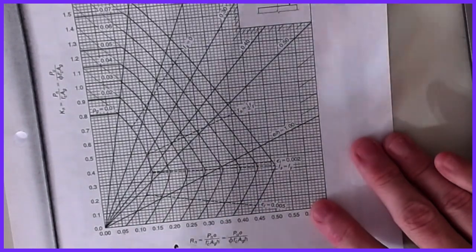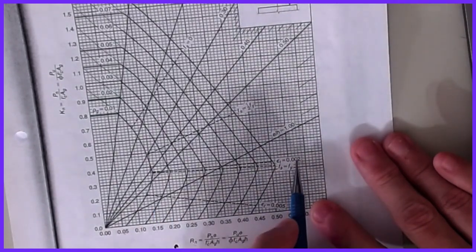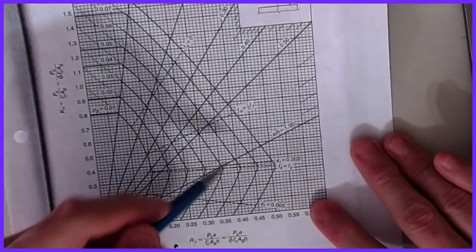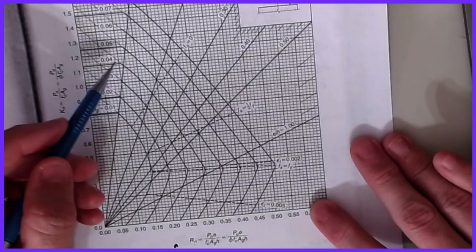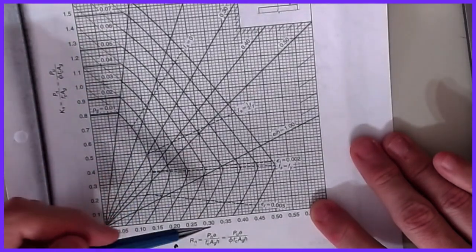You're still bound by those same rules that we set up with SRR and DRR. They also include a line here that is epsilon T of 0.002. Okay, so that would be the lower limit on this. So if I'm above this line, then I'm using a phi of 0.65 on the flexure case. Okay, and so that's what's being factored into those.